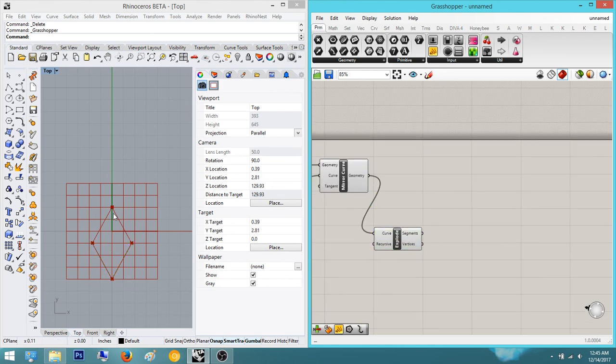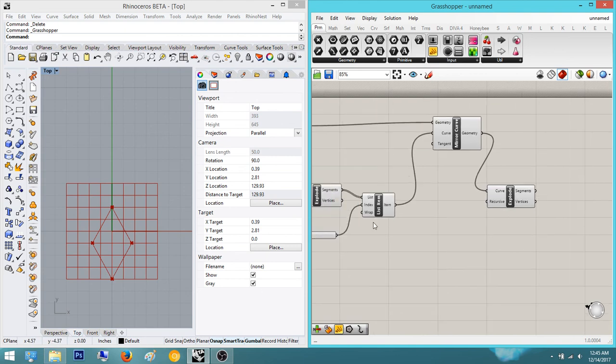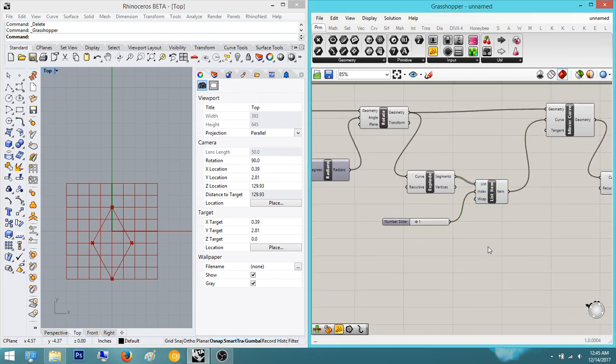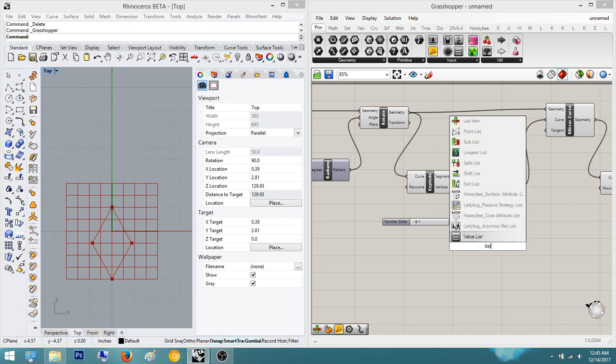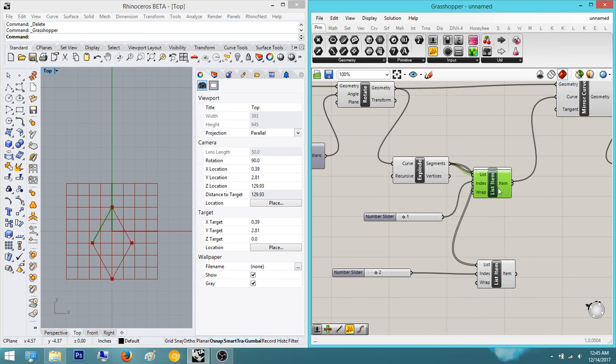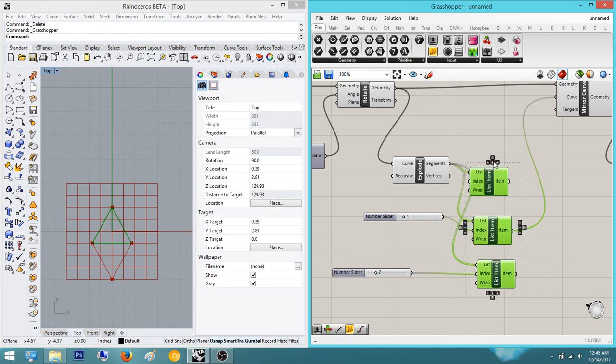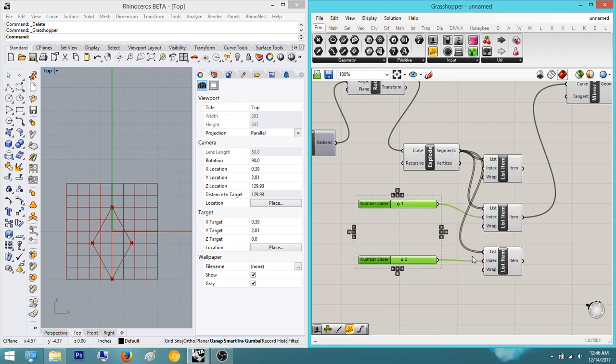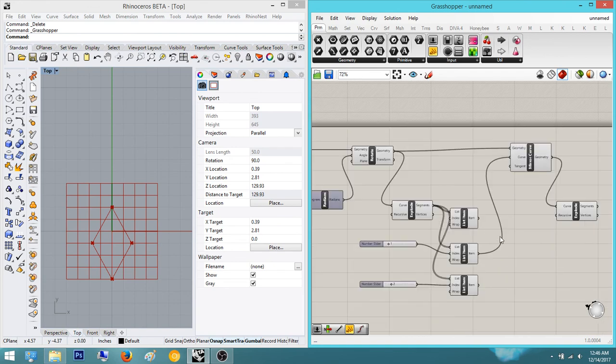So the way to do that is we're going to list item each one of these points. So for here, all I did was list item 1. So let's list item the other 2 sides. So list item, and this one will be 0. And I'll type in a 2 for the next one. List item, segments, and 2. I'm going to put this in order. So 0, 1, 2. And you can also click this button right here to straighten this out. Apparently it's called Mr. Sparkle, but okay, I didn't know that. And yeah, cool. It just keeps the script somewhat neat.